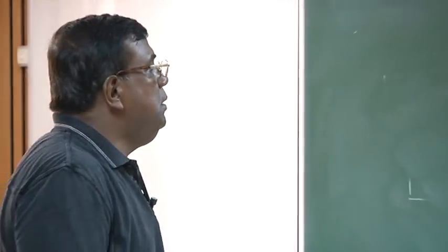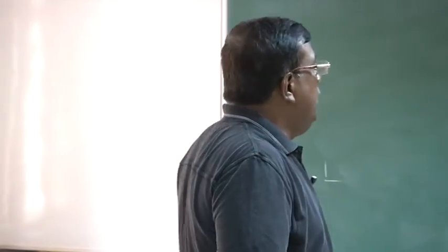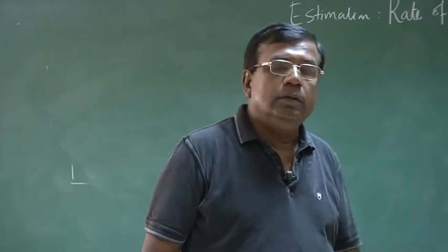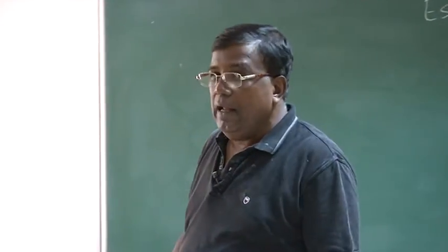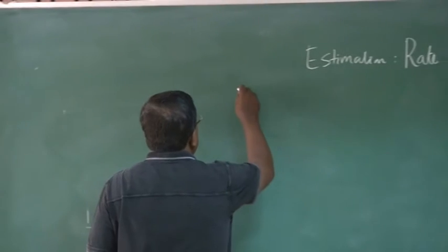We have seen how to estimate the drag polar through flight test. Now we'll also try to find out the rate of climb parameters, like what is the speed for best rate of climb, and how one will find service ceiling through flight test. Before you do that, let us recapitulate. What do we understand by rate of climb?